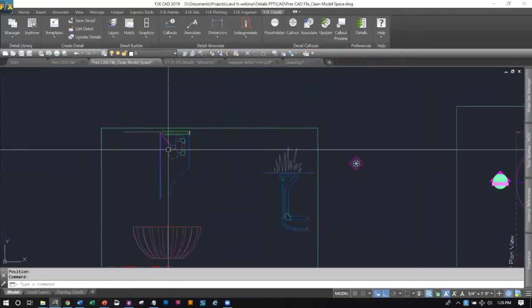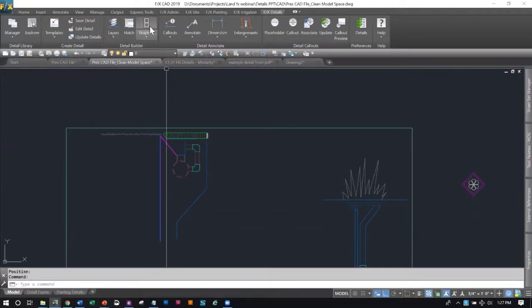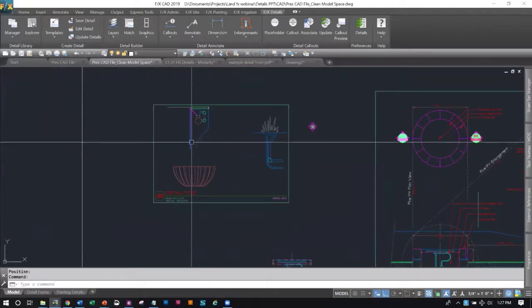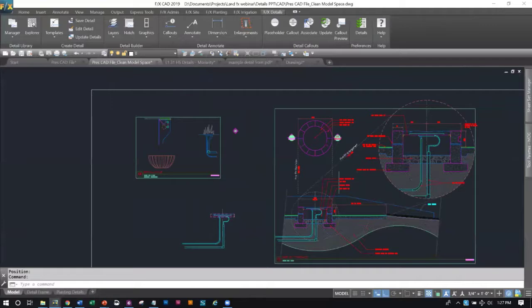I do the same thing with different pool coping. I've got a perimeter overflow, kind of a Lautner edge. We do a lot of those. I've got the basic formwork built in there, and then I can customize that. Is it going to be a stone edge or a wood edge? Or are they going to use grass? Are they going to use another material for that edge? But I've at least got a starting point, and that streamlines building your detail. You can also plug in different pots, or any manufacturer's detail that you use a lot. Land Effects has different hardware components built into it. I use those a little bit, but what I find most useful are the components of the detail that streamline building it.